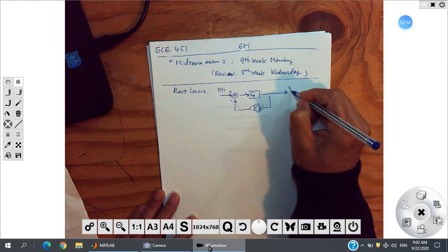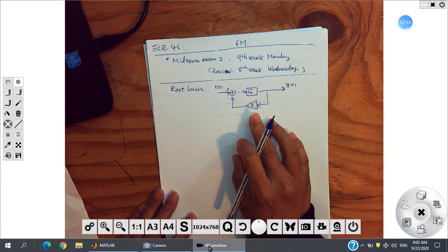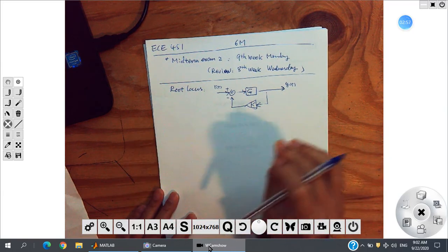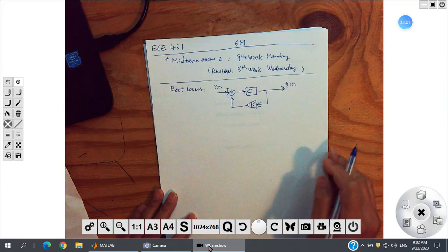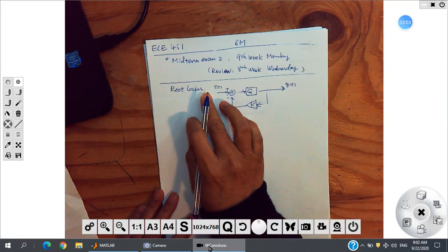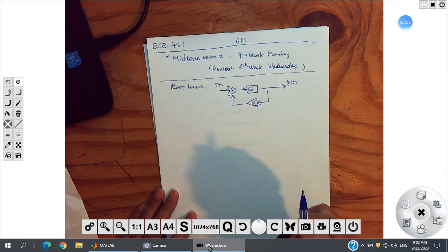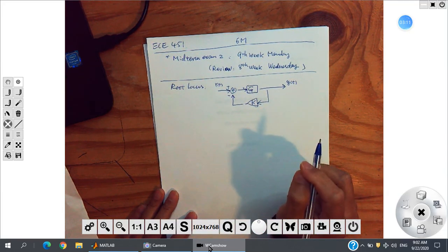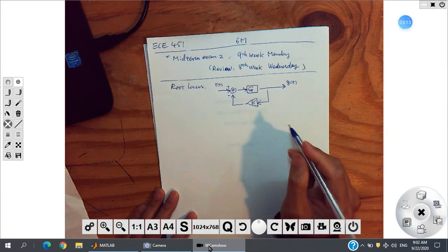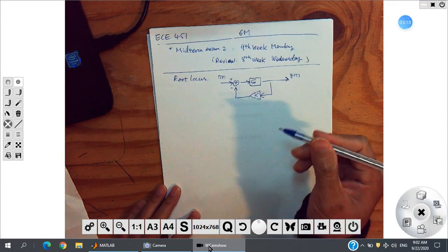Then we can have the orbit of the poles of the whole system, and that gives us the root locus. Last time we discussed the departure and arrival direction of the root locus, and to do that we need that formula.